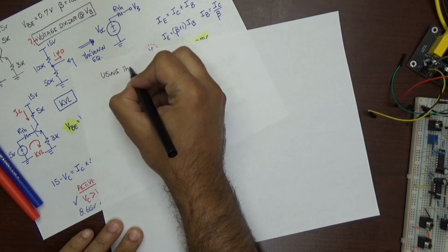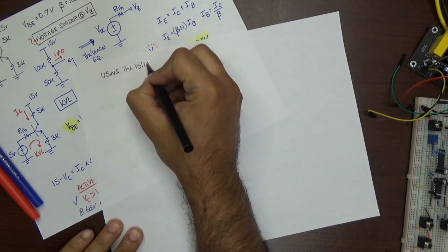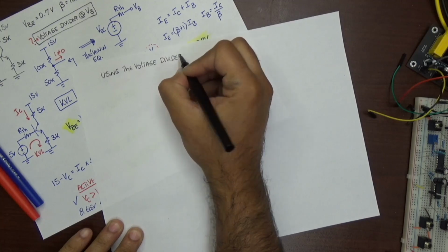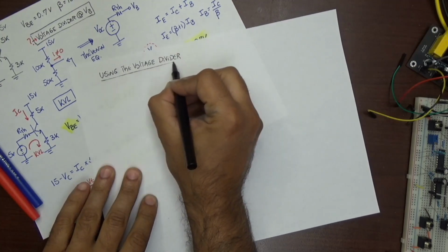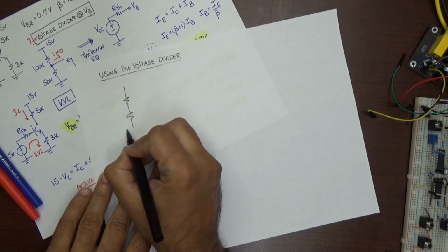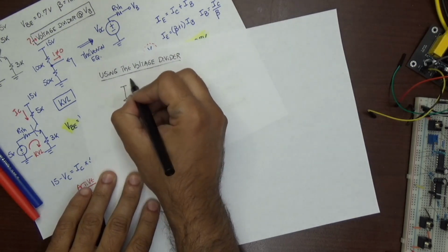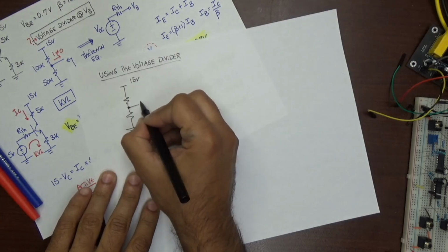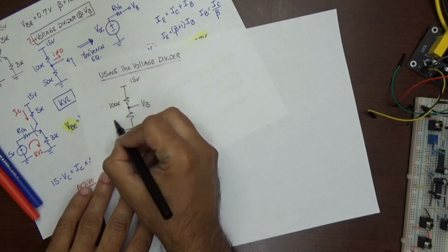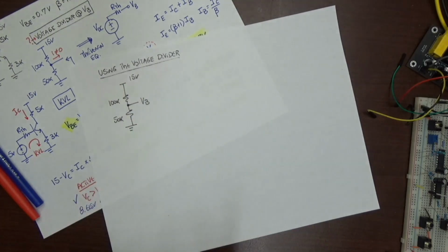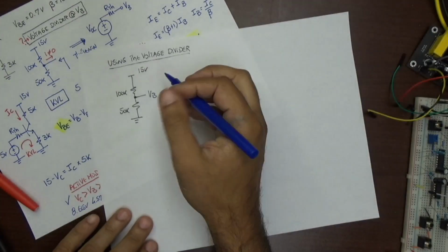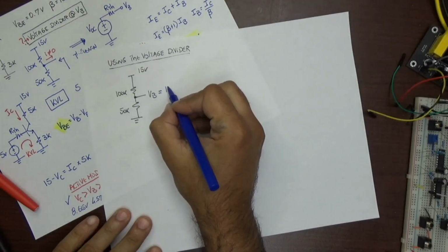All right, I'm just going to write these for us to follow what I'm doing. And we have now the voltage divider. The current that flows through the base is considered 0, so that means that that point is the VB. And I can apply directly my voltage divider, which is equivalent to calculating the open circuit voltage for your Thevenin, which is 5 volts.